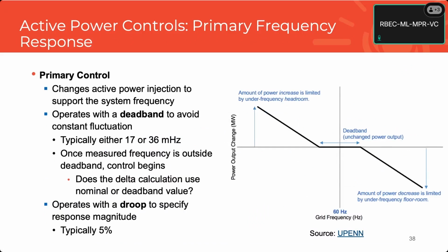Right. Yeah. So in this section here, this is our deadband for frequency power control. In this area, there's no one defined operating point. Basically, your power output will stay constant for any frequency, while there is no one frequency for a given power. So everybody can do whatever they want with their power, as long as the frequency is between plus or minus, say, 36 millihertz in either direction.